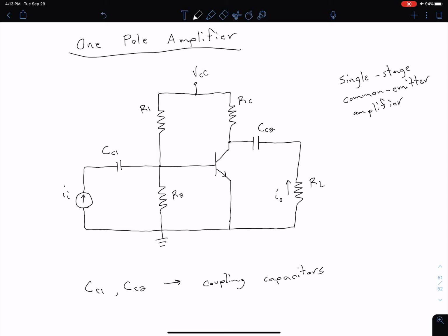What we're going to do in the next few videos is look at various amplifier configurations in order to determine our small signal gain. So keep in mind, in the previous video we said we're ultimately concerned with our loop gain, but remember that our loop gain is just equal to our gain times our beta term. So even though right now we're going to be investigating our gain for a given amplifier configuration, we can easily convert this to a loop gain just by multiplying by that beta.